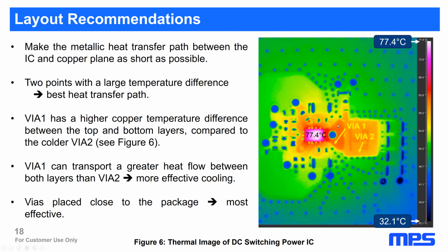Because this area has to be very small, this polygon, because of EMC. It's a fast changing voltage. And the inductance acts as a heat sink for the silicon. Heat will flow on this short way to the inductance, will additionally heat up the inductor, and this cools down the IC.